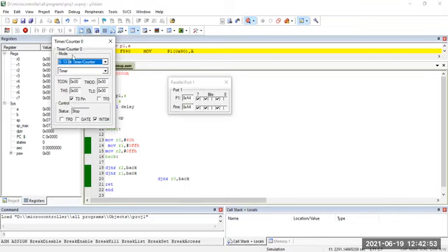This is in mode 0 now, that's why it is a 13-bit counter. You can select here. Mode 0 means it is a 13-bit counter. Mode 1 means 16-bit counter. Mode 2, 8-bit counter with auto reload. Mode 3 is actually two 8-bit counters, but we are not going to use this one. That is not there in your syllabus, that's why I didn't teach it.